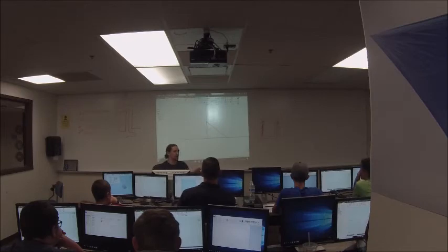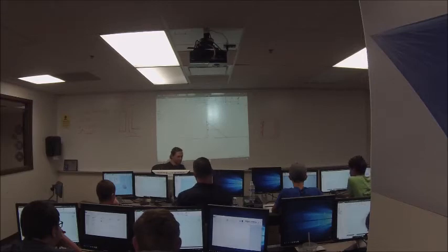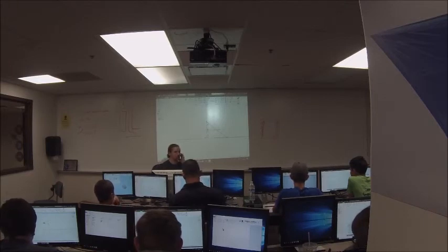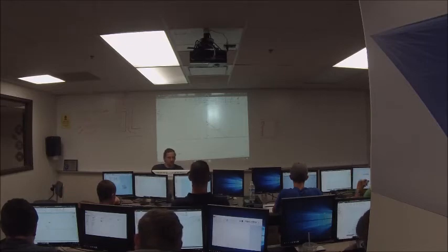So it's a little bit finicky. It can be kind of a pain in the butt to delete constraints. But hover over the constraints with your mouse, and you have to left click first, and then don't move your mouse, and then right click. You've got to left click first, then right click, and that's in your handout. If you forget how to do it, it's in there. But left click on the icon, then right click without moving your mouse. Then you can go up and hit delete, and it'll delete the constraint.